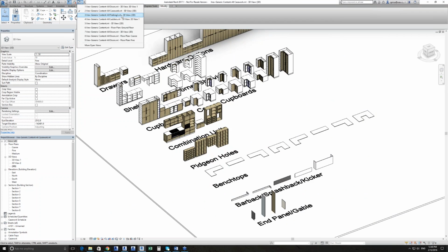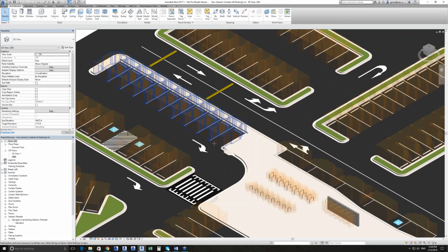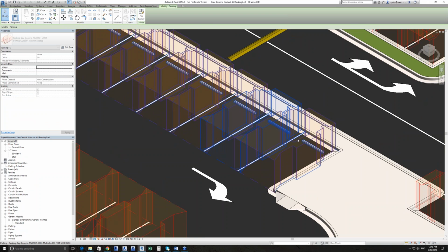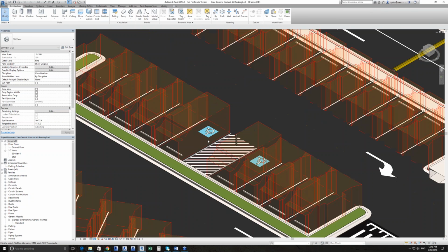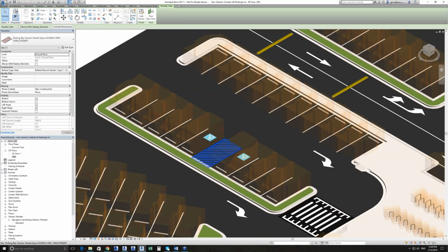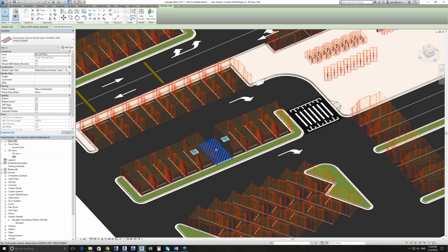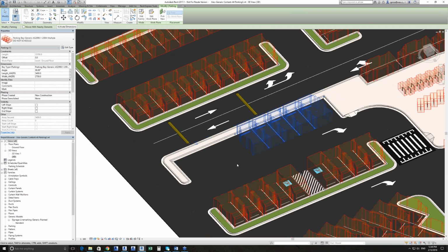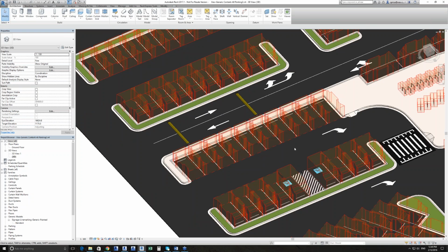So then there's the parking suite. So again, like the door suite, the parking suite has these 3D clearance zones built into them. So you can see in here we have our AS2890 parking envelope built in, and similarly for disabled parking bays, you can see we also have that 3D clearance allowed in there. We have ones set up for our shared spaces as well, and they can be rotated. So this is a 90-degree bay, but if it's a 60-degree or a 45-degree bay, then all this will automatically rotate and resize. So all the line work is smart, and the bollard automatically sits in the correct location as per the code. These are set up as line-based families, so they're really easy to go and adjust to the appropriate lengths. I grab the right end, like so. So within that suite you get all those.